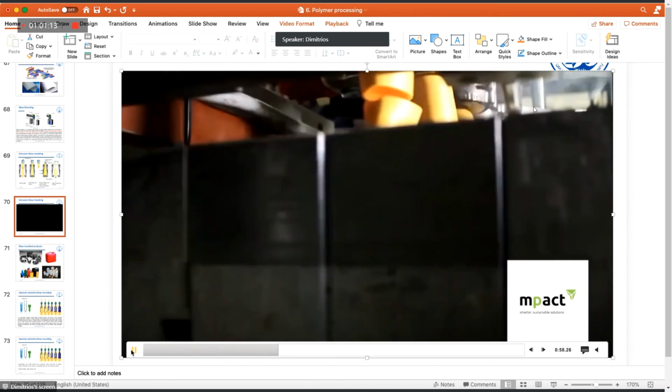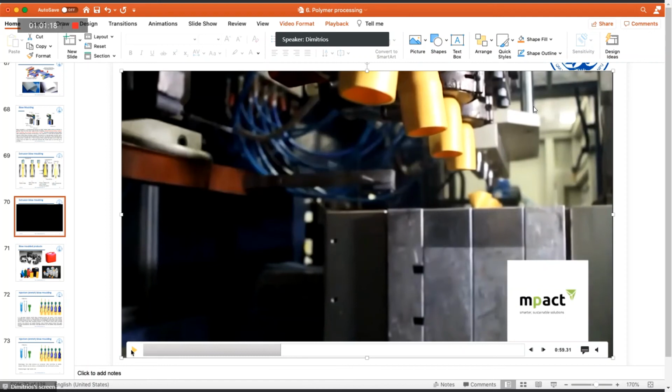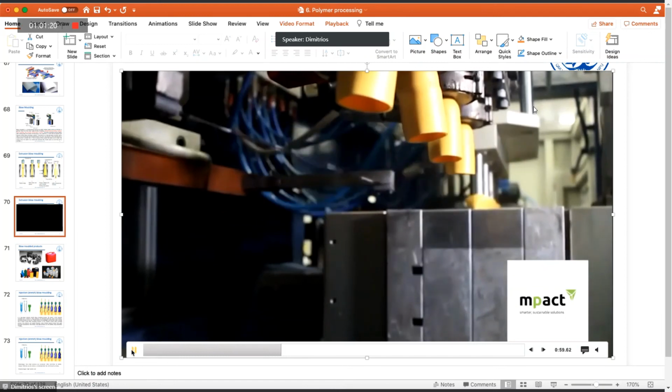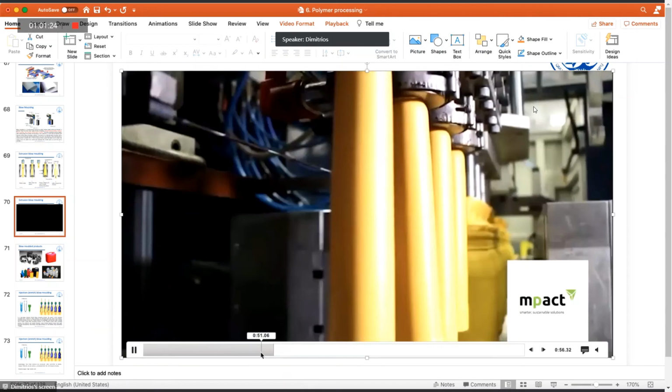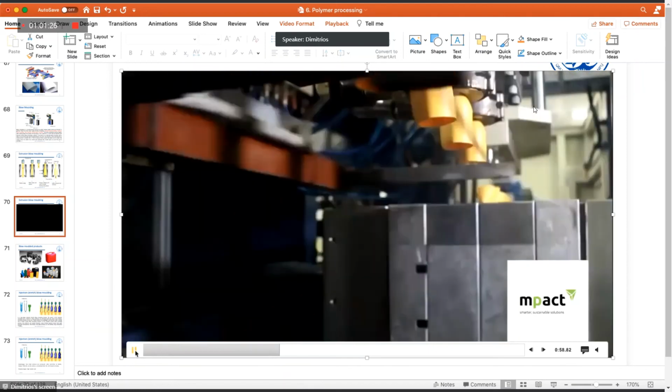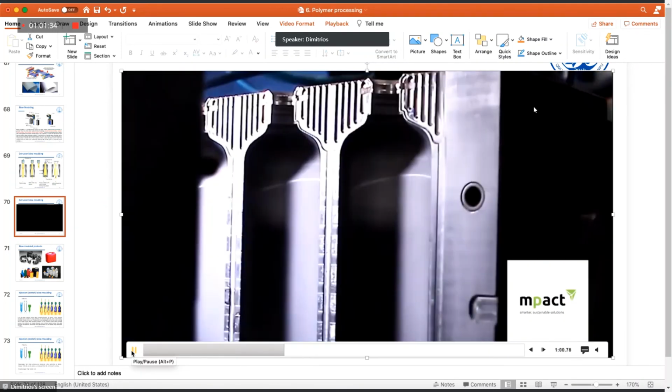Here is where air is blown onto the bottles, and then we have the formation of the bottles after we open our mold. We cool down the mold, of course, in order to solidify completely our material. And then we want to cut any excess material, such as this one. So there are specialized knives. You see how they cut them.